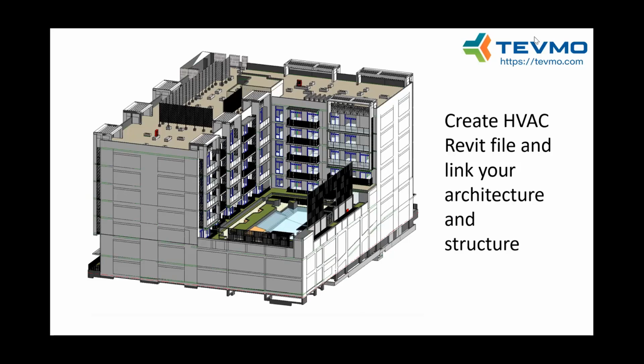So the first thing you need is architecture and structure in Revit. Then you create an HVAC Revit file and link your architecture and structure. If your engineers work in Revit, not only architects, then probably you know this part, and you always link the architectural file. The thing is that our plugin, our software, works with HVAC files. So you don't need to change anything in the architectural structure. You just need to make some changes in the HVAC file.